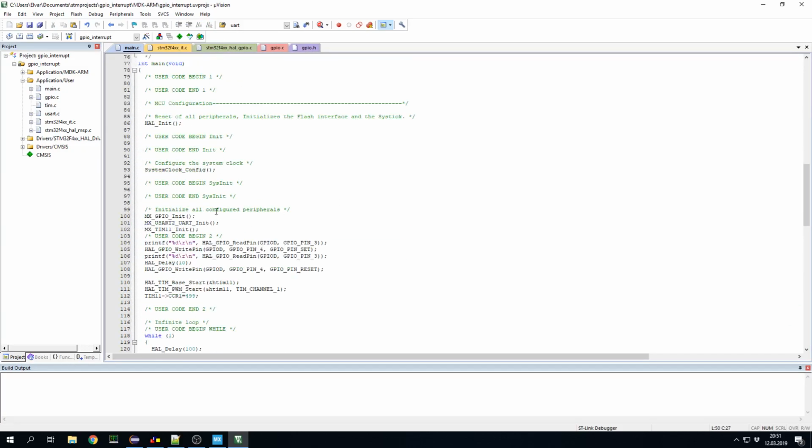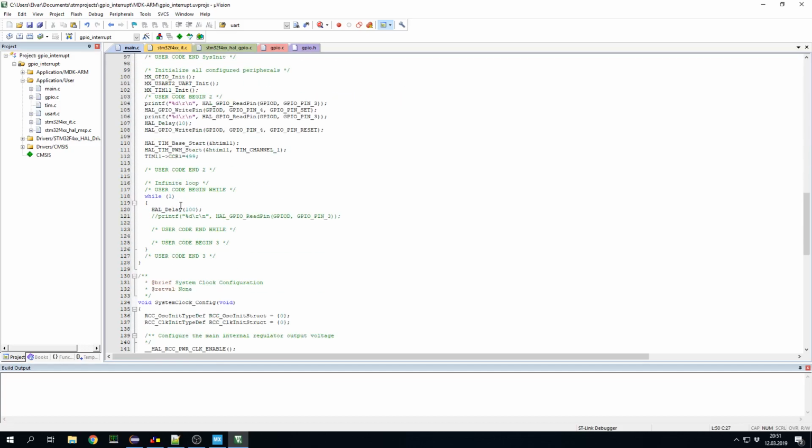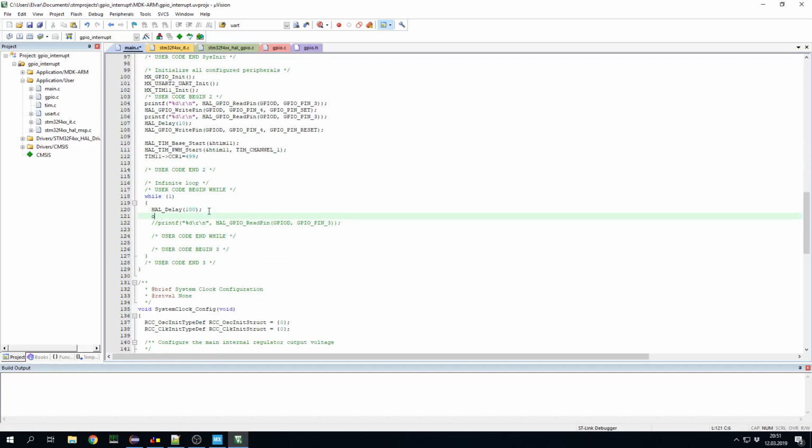So, what I want to do here is, after every 100 milliseconds, I'm gonna print. I'm gonna do it not every 100, I'm gonna do it 99, because I think the printf will also take 1 millisecond of time. Let's see. And counter. And this is a counter. So it should now print out the value of the counter after 100 milliseconds.